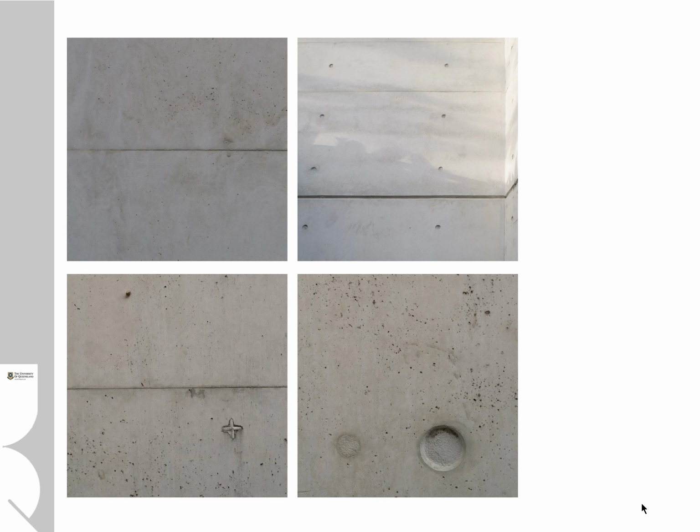But when you get a closer look, you can start to see where the joins between the two panels of the formwork have come together and result in a slight overlap and a lip where they haven't quite aligned properly. Now again, this is always very difficult to control with in situ concrete, and often you just have to accept it and perhaps incorporate that into the detail.